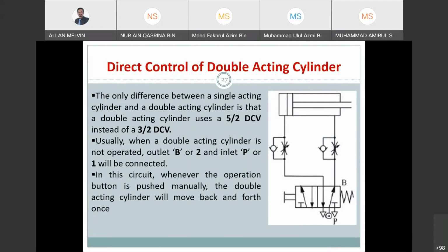Yeah, maybe you can refer to your friends, some of them managed to get that. If you change a few of the rollers to idle roller, it will solve it. Just make sure you're switching the sequence like I told you earlier.